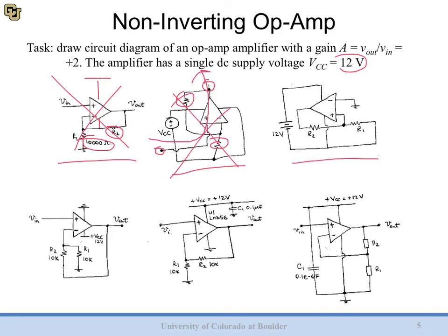This third attempt over here is again very confusing. When you just look at the circuit immediately, it's not clear where the input and where the output are. Turns out this is the input and this is the output, but it's not readily clear just by glancing at it. We also don't have component values for our resistors, as well as the fact that if we follow the data flow, we're kind of going from the middle to the left. That's non-standard, very confusing. We don't like this at all. The fact that we used a battery for our voltage source is actually fine, because we may implement that as a battery.